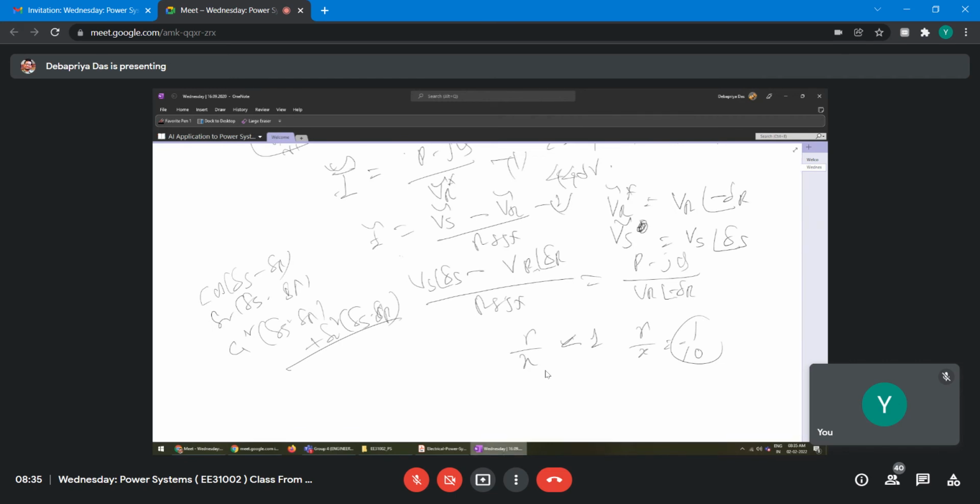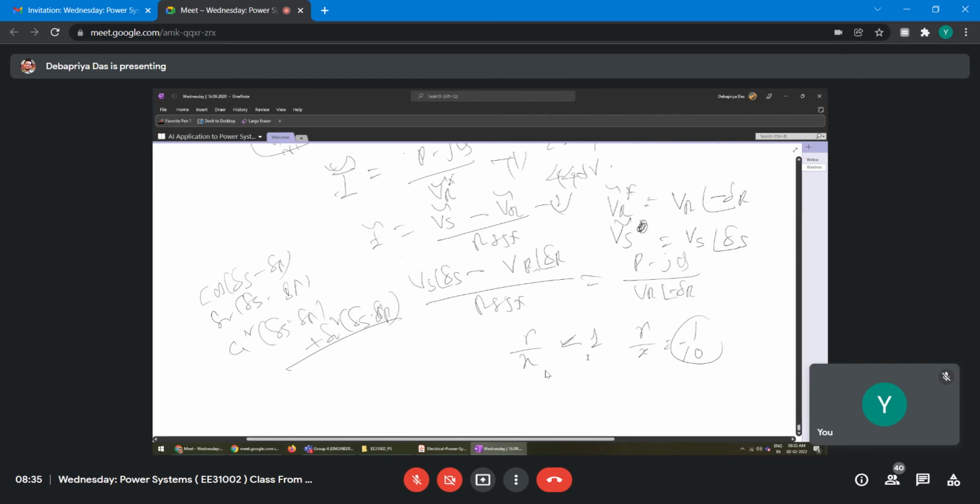And another thing, let me tell you, in detailed analysis for a high tension transmission line, whatever you do, this reactance, even for 11 kV to 220 kV, whatever may be the configuration, generally, if I recall correctly, it varies actually 0.27 ohm to 0.35 ohm per kilometer, right? So reactance has not much variation even from low tension to high tension, but 0.27 ohm to 0.35 ohm per kilometer.